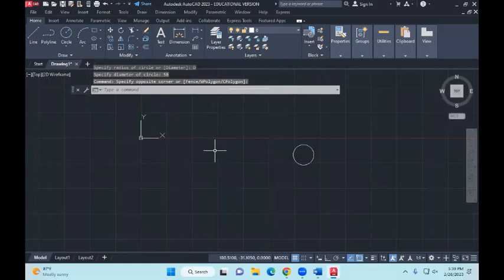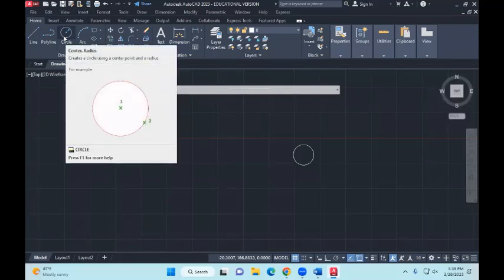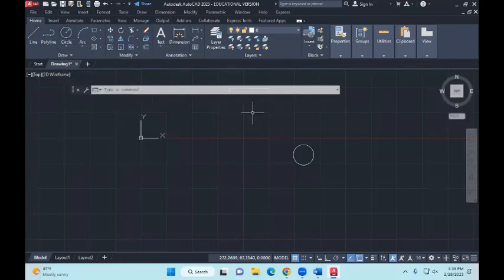After you have drawn the circle, the circle command ends, unlike the line command, which carries on. If you need to draw another circle, you have to restart again: C, circle, enter. So we've just gotten started with lines and circles. That's how you use your drawing area.